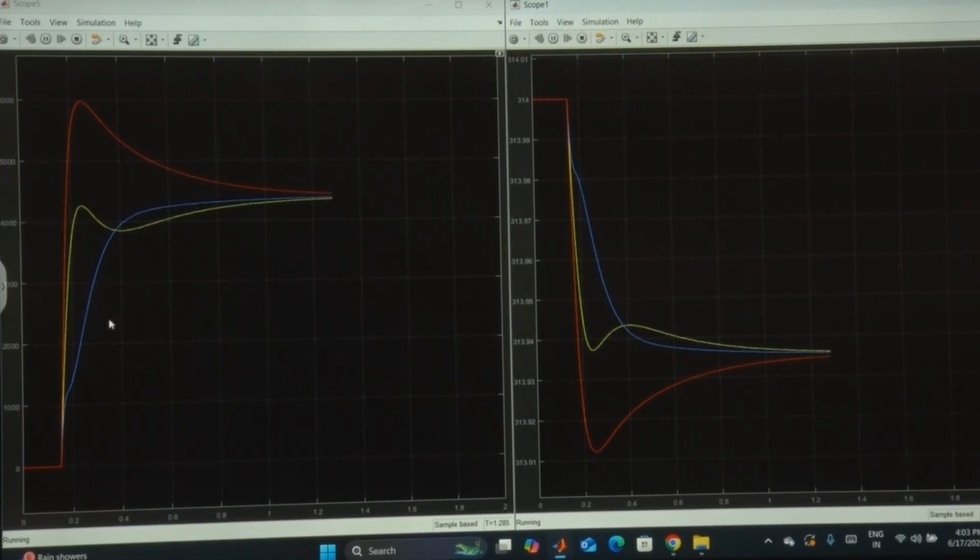So you see here, like this one, the color, this is increasing. What happens? Because the load is fixed, the first source has no choice but to automatically reduce its power. So its power starts to reduce. As its power reduces, its frequency starts to go up, while the other frequencies start to go down. And now they become the same at some point. So frequencies become the same, powers become the same. This is how the primary control and group control works.